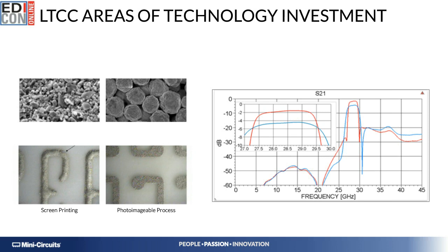On the other hand, a photoimaginable screen printing process delivers much smoother conductor traces, fine-line definitions, allows for much tighter spacings between conductors, along with a much higher silver concentration of the paste. This translates into the possibility of realizing tighter couplings, reducing lot-to-lot, unit-to-unit variations, significantly reducing insertion losses by having much smoother and higher conductivity conductors.